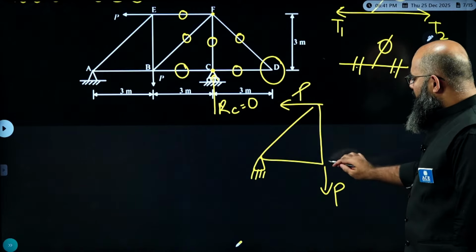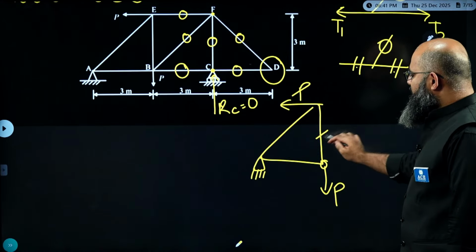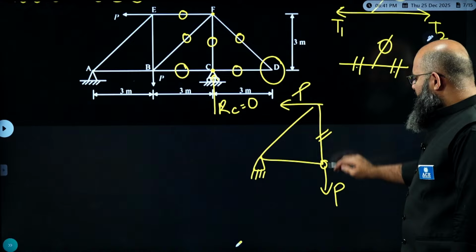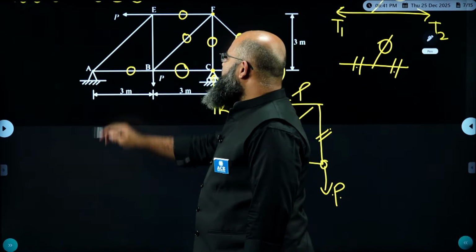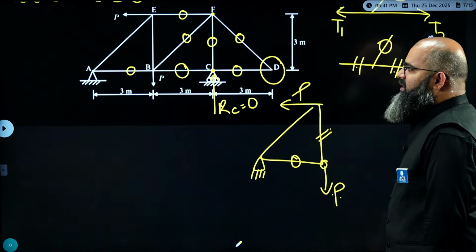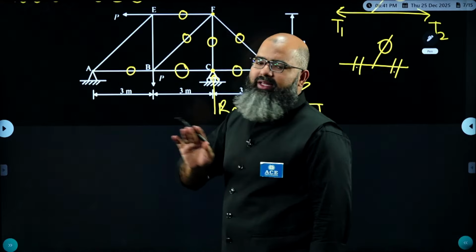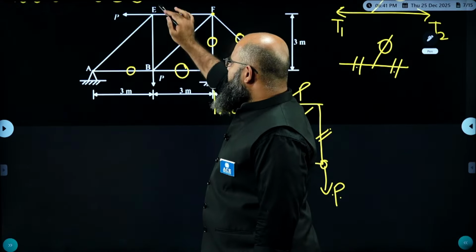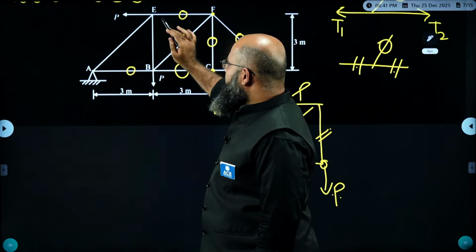Okay. Now come to this particular joint. At this particular joint, this loading and this loading are collinear. He is the only loading non-collinear. So this and this both are equal and this is equal to 0. That means this member also is a zero force member. Only remaining members are BE and AE member. Both of them are non-zero force members. Okay, BE is going to experience a tensile kind of loading over here.